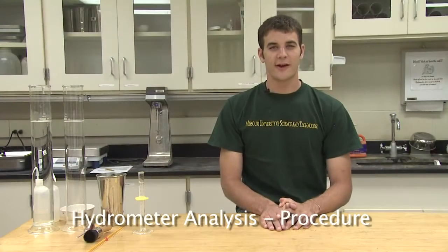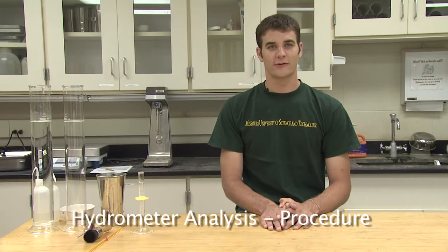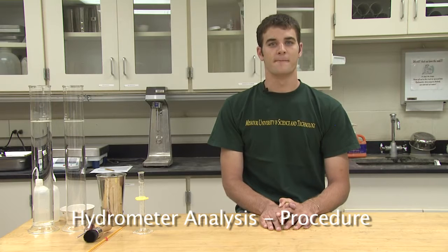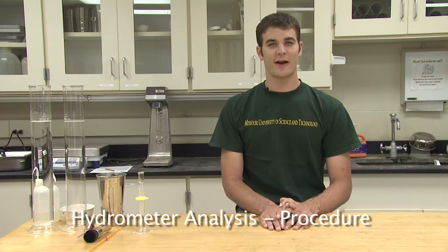To determine the particle size distribution of the soil particles finer than the number 200 sieve, a hydrometer analysis must be conducted. The hydrometer analysis measures the change in specific gravity of a soil-water mixture over time. As soil particles fall out of suspension, the specific gravity of the soil-water mixture decreases. The application of Stokes' law to falling spheres is used to determine the grain size distribution of the particles falling